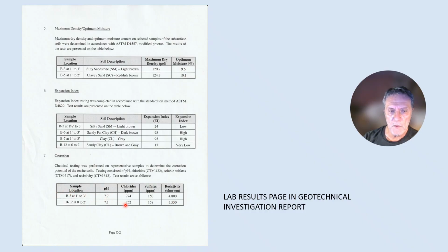Corrosion: these are primarily chemical tests for pH, acidity, chloride content, and sulfates content. The corrosion tests are run on soils to see whether the soils will corrode metal structures like culverts, pipes, beams even. So if they are shown to be corrosive soil, you can undergo some chemical modification or replacement of these soils.